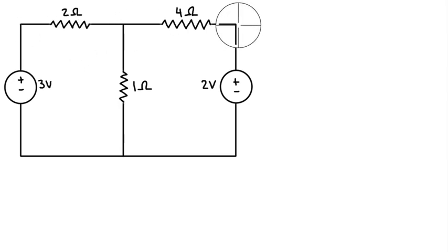And what we want to do in nodal analysis is we want to pick one node to ground it. It's not really a real ground, but it's just the reference that we're going to take as 0 volts for all of the other voltages. And in cases with voltage sources, especially more than one voltage source, if you can ground the node that's connected to one or more than one voltage source, that's going to be a good one for us to take reference. So let's draw on a ground here. So this node is going to become our 0 voltage for the rest of the problem.